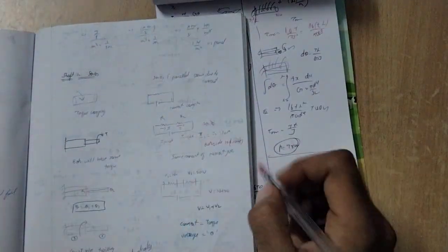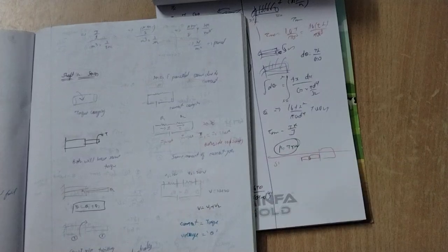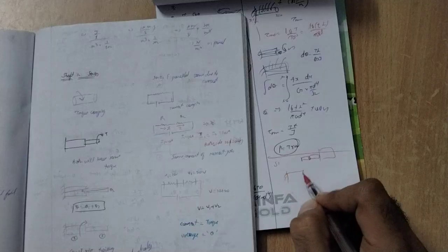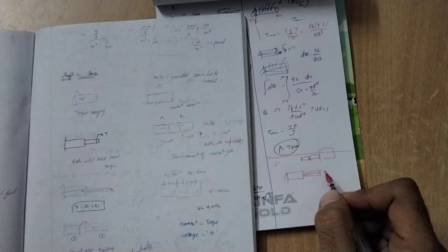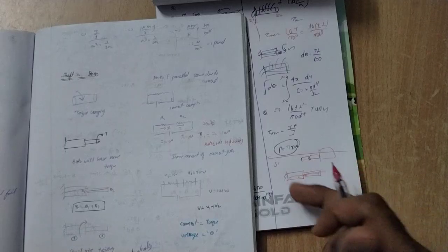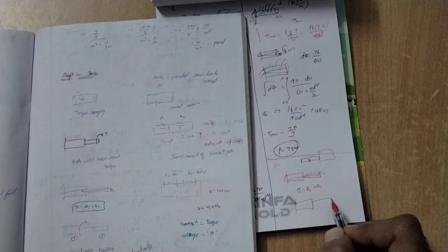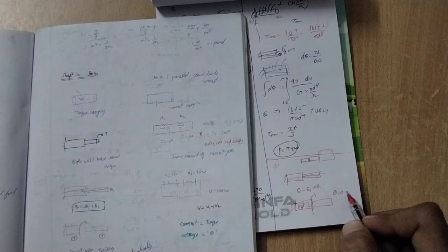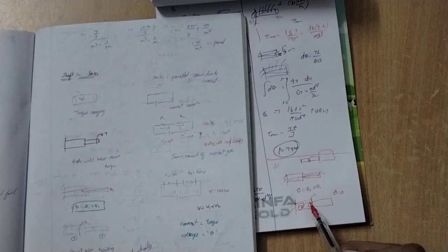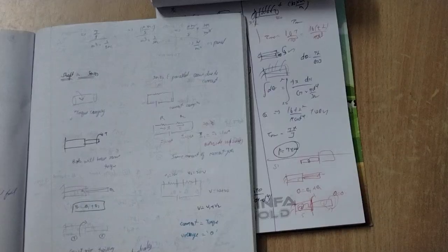Next one is shaft in series. Okay, series means this is a series. So you can see whenever we apply the torque, this will change by a θ1 and this will change by a θ2. This will rotate so much and this will rotate so much less. So θ equals θ1 plus θ2. Whenever the torque is applied here in this location, this dominates the move. So θ equals θ1. Okay, it means if this rotates 5 degrees, this one also rotates 5 degrees, because we are not applying the torque here, we are applying the torque here. Okay, I think you got the point.